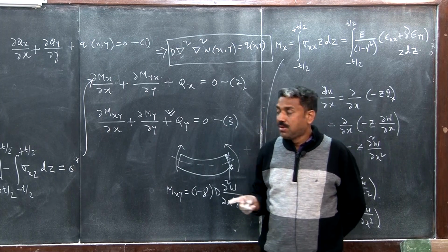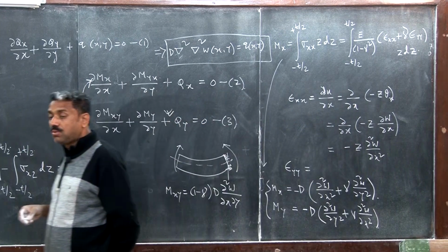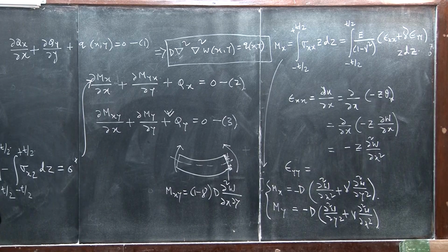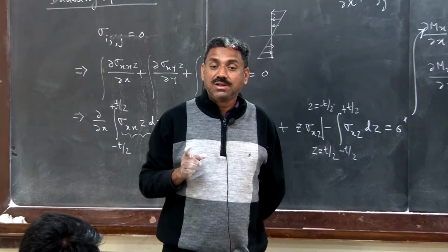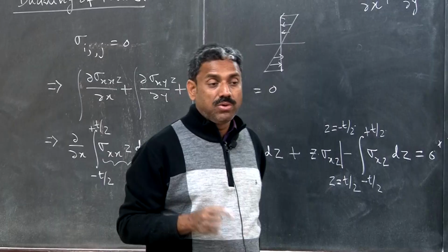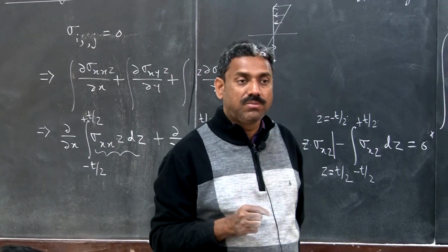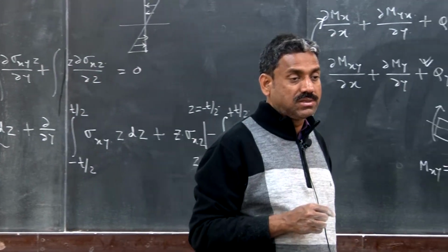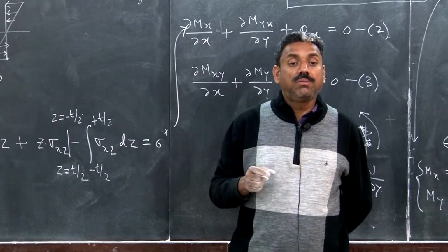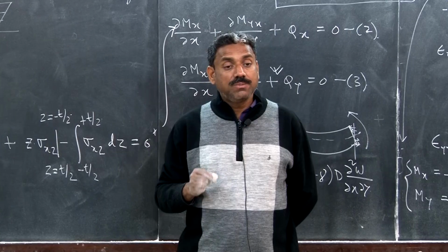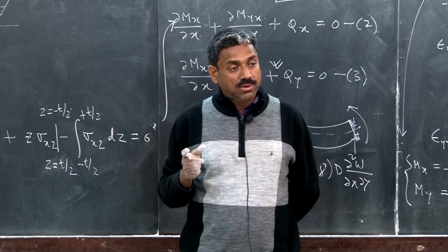Okay. Now, having the plate bending theory known, we have to go one step ahead, because we now want to study the stability of the plate, right? So for stability of the plate, all these things we have done, we were considering equilibrium in the undeformed, unperturbed configuration. But when we want to study stability, we have to consider equilibrium in the deformed configuration. We have to consider an a priori deformed configuration of the plate.